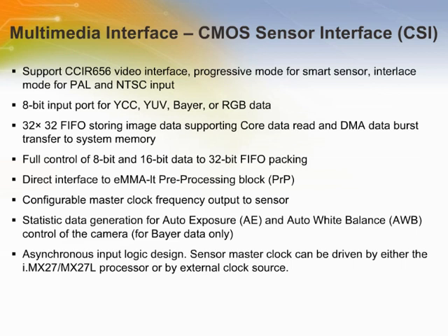The sensor port supports a direct parallel interface to either CMOS or CCD sensor controllers using a parallel interface with widths of 15 bits, 10 bits, 8 bits, or 4 bits at data bus rates of up to 60 MHz. The sensor port may be configured to output a still image to non-contiguous memory buffers, enabling efficient memory use under an open OS.